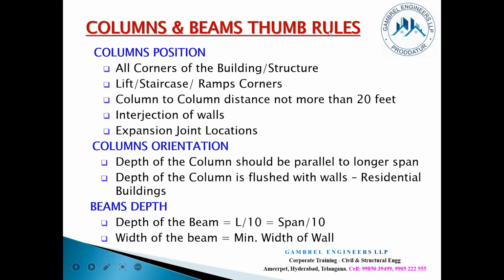Yes. Now, column positions and then column orientation. Column position guidelines are given here. How do you position the columns? First thing, all corners of the building are structural, so they have to keep columns on all the corners of the building. First point. Next, if there is a staircase, ramp, or lift, you provide 4 columns on the 4 corners,